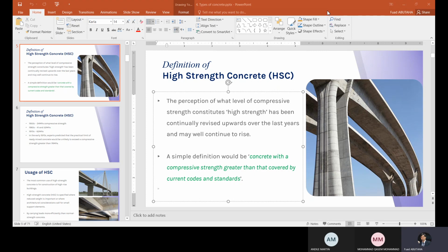So if you know that if I increase the particle size of aggregate, I can improve the workability of concrete a little, and the amount of super plasticizer can be reduced. So I will use less super plasticizer, and I can save significant cost in the production of this concrete, because the most expensive among all of this is the chemical admixture, super plasticizer, which they add in a small dosage.